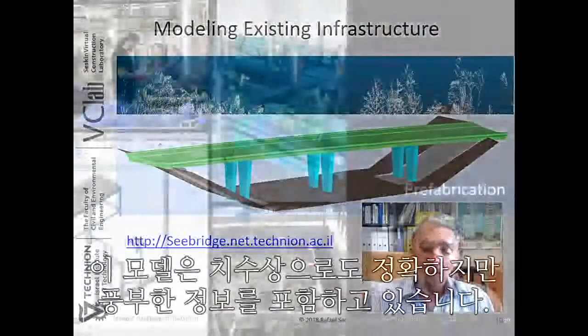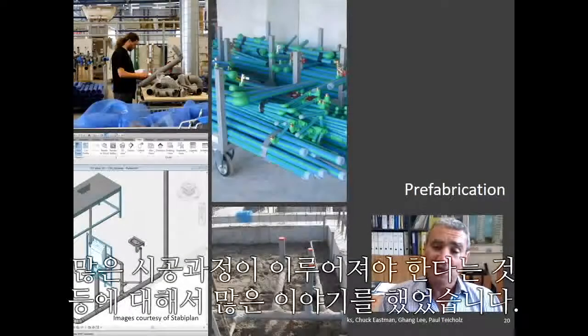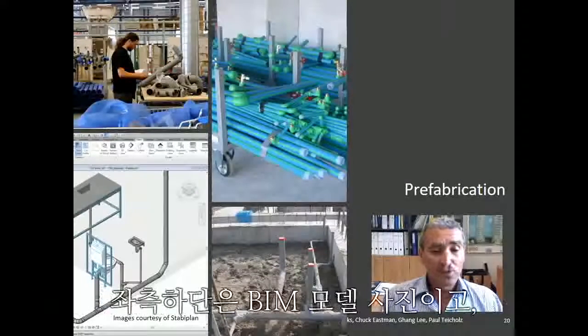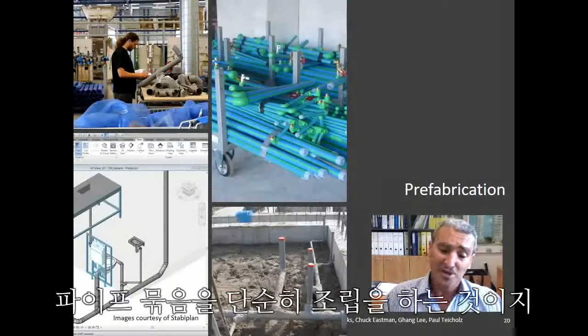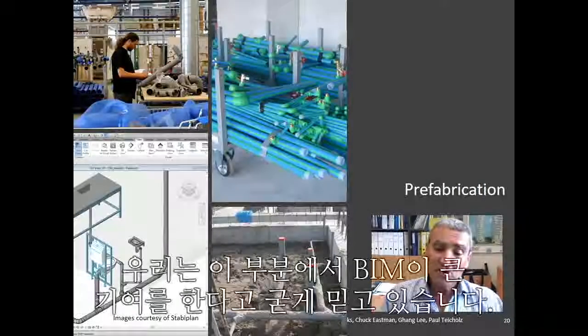Already in the first edition, we spoke a great deal about the ideas of fabrication and of being able to shift as much construction off the site as possible. In this slide, you see an example from the book in chapter 7, where you see the BIM model on the bottom left. You then see a worker in a fabrication shop preparing pipe spools. They're assembled on racks and delivered labeled to the site, where it becomes a matter of installation and erection rather than one of fabrication and manufacture. And we believe strongly that BIM is going to contribute greatly in this area.